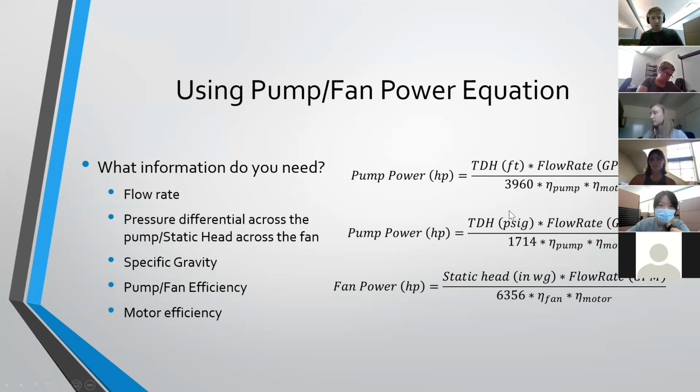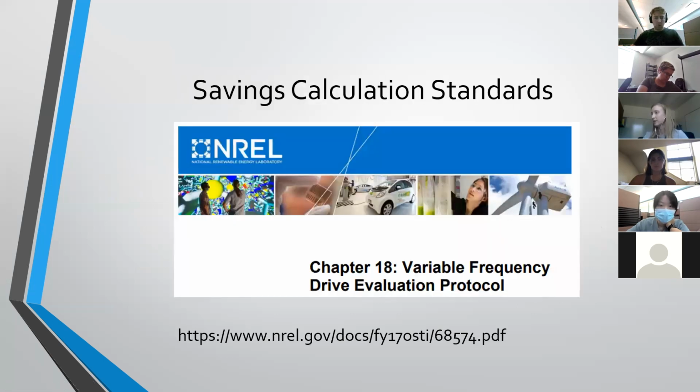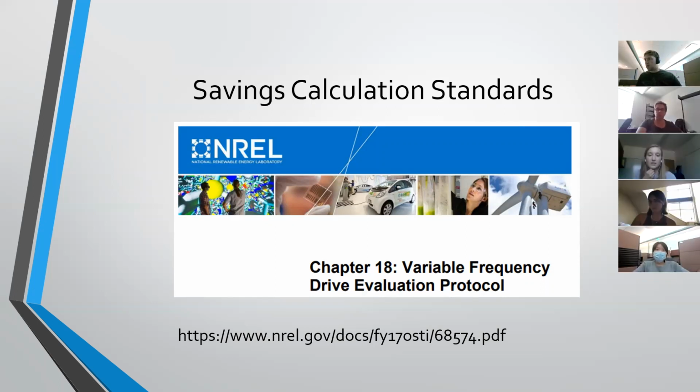So yes, we'll move on. Now you've determined your baseline power usage, either through the pump power equation or through logging amperage data. Now, how do you actually figure out what energy you're going to save by using a VFD? NREL has a protocol that they've come up with to calculate VFD savings, which is super helpful. So if you're diving into VFDs for the first time, I totally recommend that.